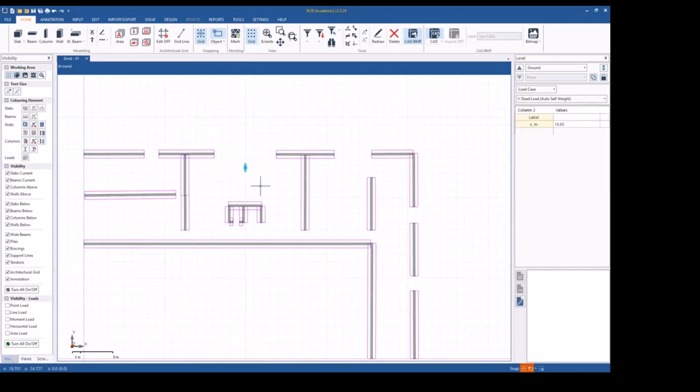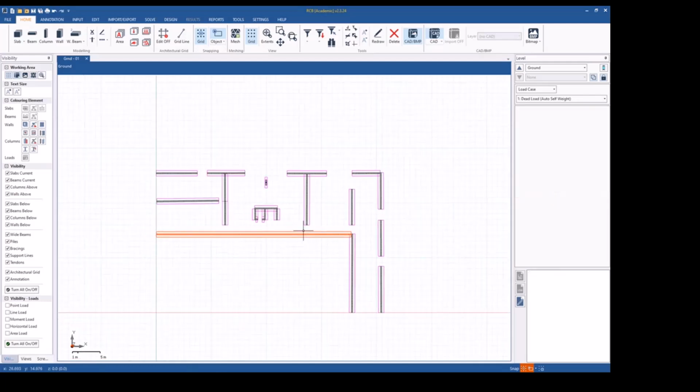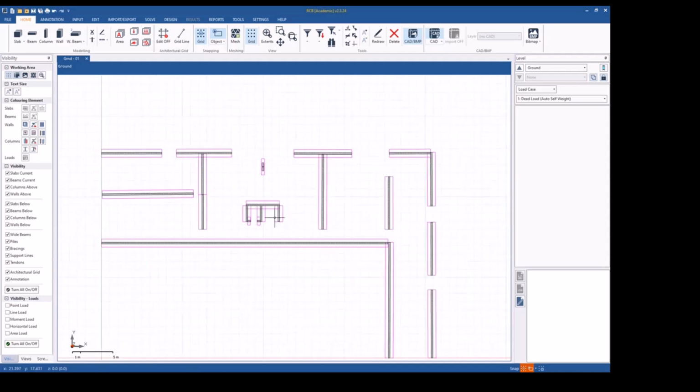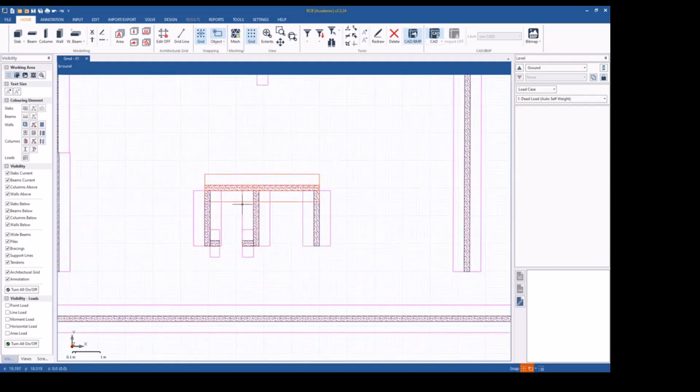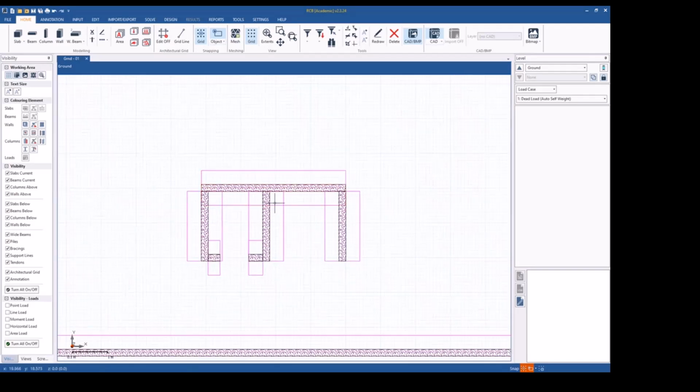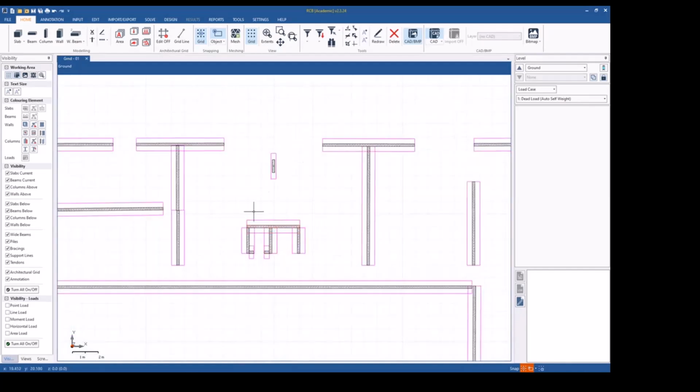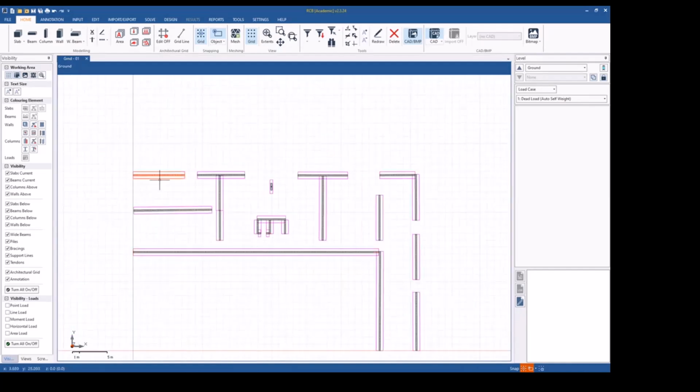So we just define there is a footing for those columns. And it won't matter in our modeling for what we're doing in this exercise. I don't want to change the design of the footing. I just want to tell the system that's the end of the wall. It's got a footing. Same thing here. I will just select yes. Remember, we just want to look at the dynamic behavior mostly here. And we will only be interested at the stresses we're going to get in the walls at ground level. So we will not make any setups for the full design. So it won't matter. I'm just going to tell the software that the wall's going to end there.